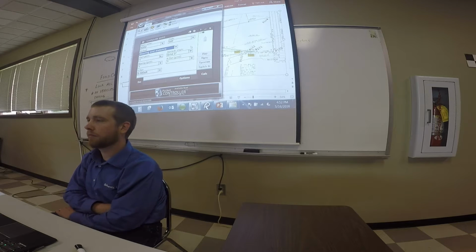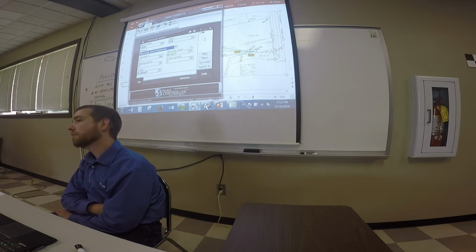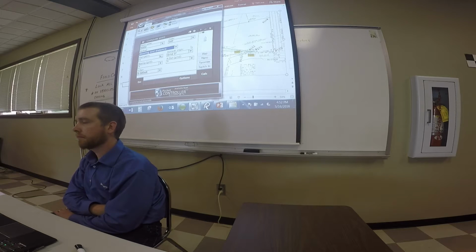If someone is giving them to you, and you're needing to look for multiple pins, it might be easier to translate and rotate and throw all that down on your data than sit there and calculate all the angle rights and distances and do that traverse on your data, right? If all you need is one, I wouldn't go through all that to get that. I'd just calculate my angle right distance, turn it off my 2-pound pins or whatever, and pop it.